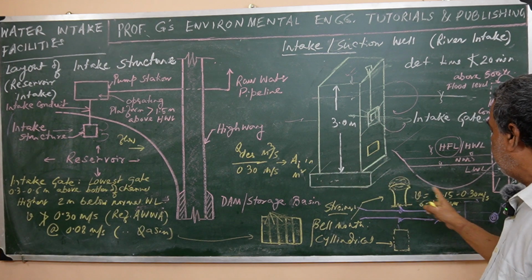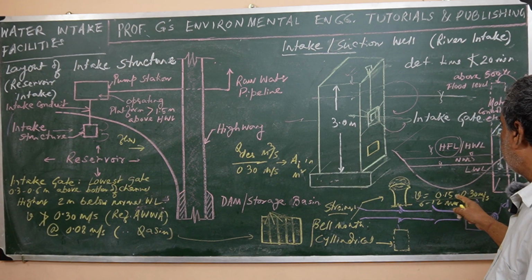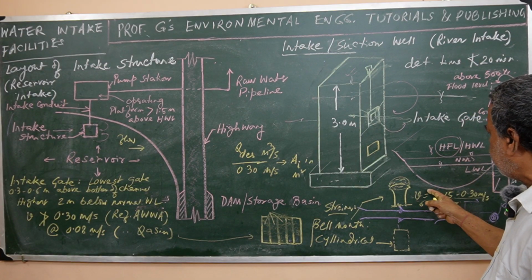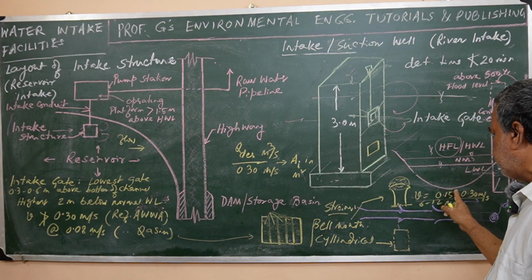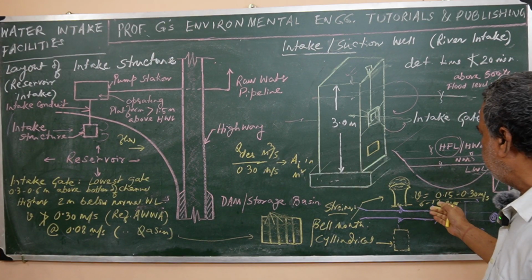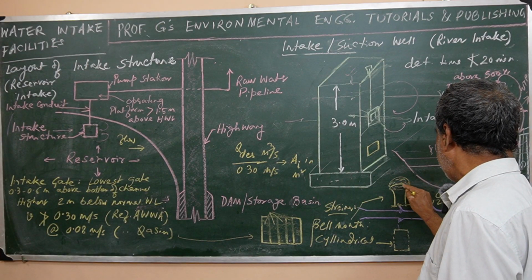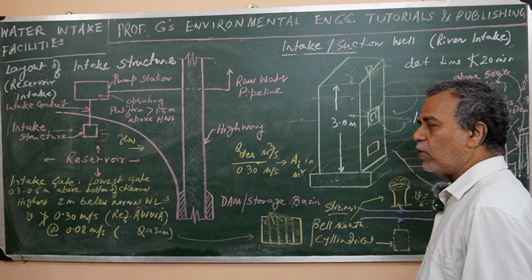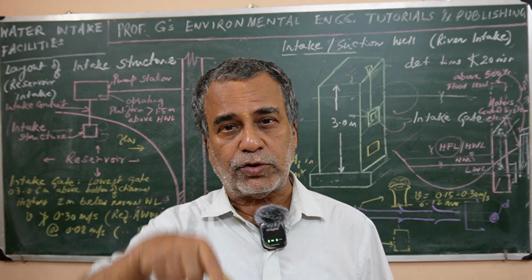So Q design by this velocity, right, and then you will get the effective area of opening. Then based on that, you know how many opening perforations are there, and what is the perforation factor, that means how many holes are there in the gross area.